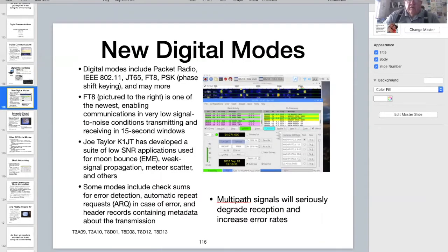There are a number of digital modes available for amateur radio operators, and many of them are designed to be used on VHF and higher frequencies. You'll need a multi-mode radio for some of these digital modes, as they are sent over single sideband emissions. There are also some that are sent over FM emissions, but you'll probably need a base station rather than a handheld radio to use them.